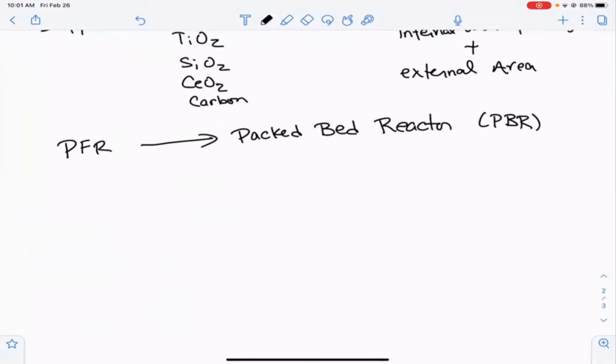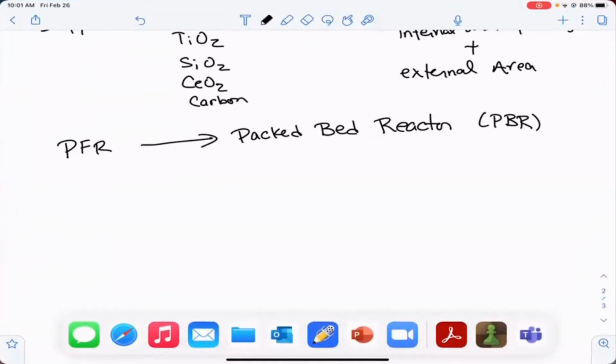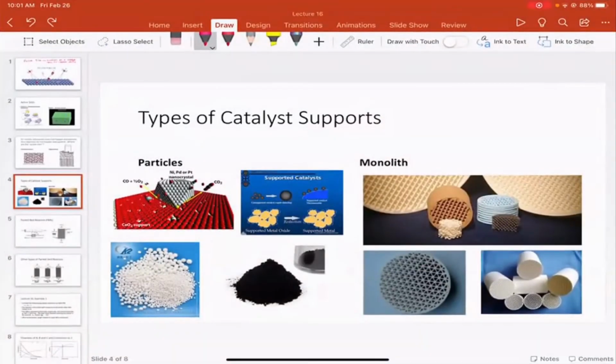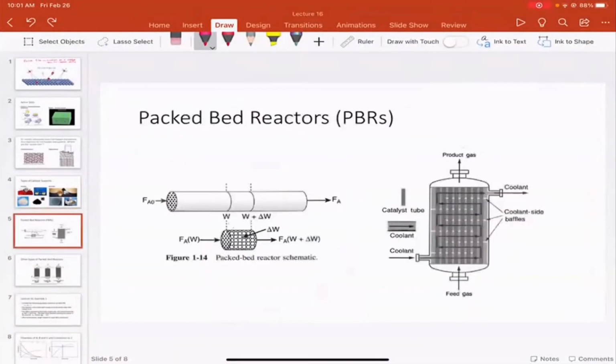Okay. And one of the interesting things that we'll talk about in a minute is that when you go to the packed bed reactor and you require a catalyst for any reaction to happen, the reactor volume is not the thing that matters anymore. Now, it has something to do with the amount of catalyst that's there. And we're going to circle back to that in just a second.